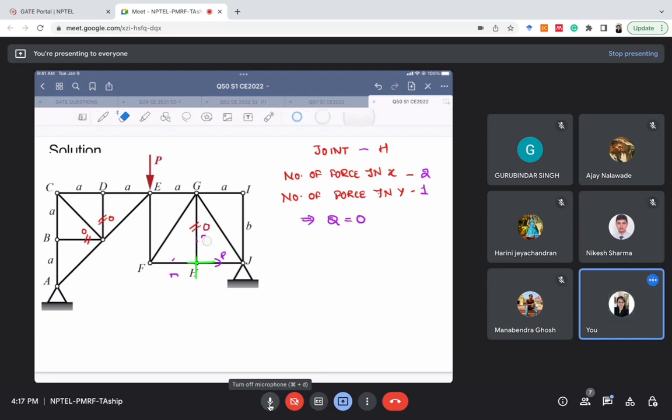You'll see in this big truss how many members are zero force members. Zero force member means all these members can be removed from the analysis. So in this step, I'll find all the zero force members possible for this structure and remove them, and then our analysis will be simplified and we can easily find the force in EF.